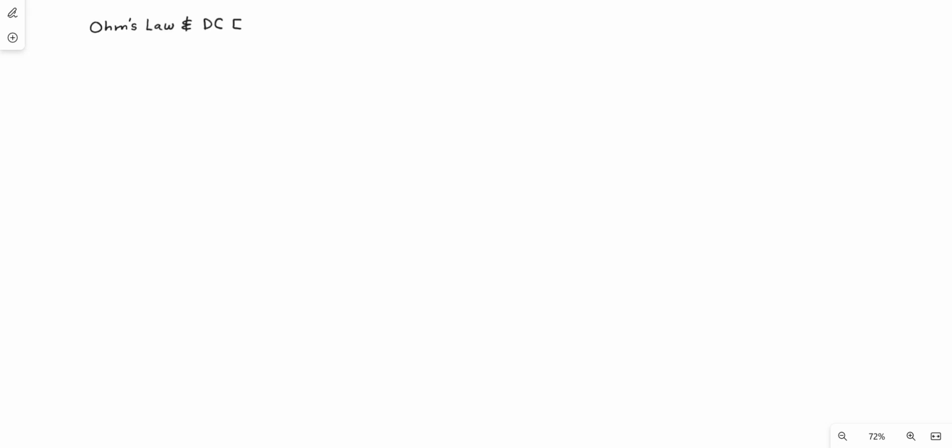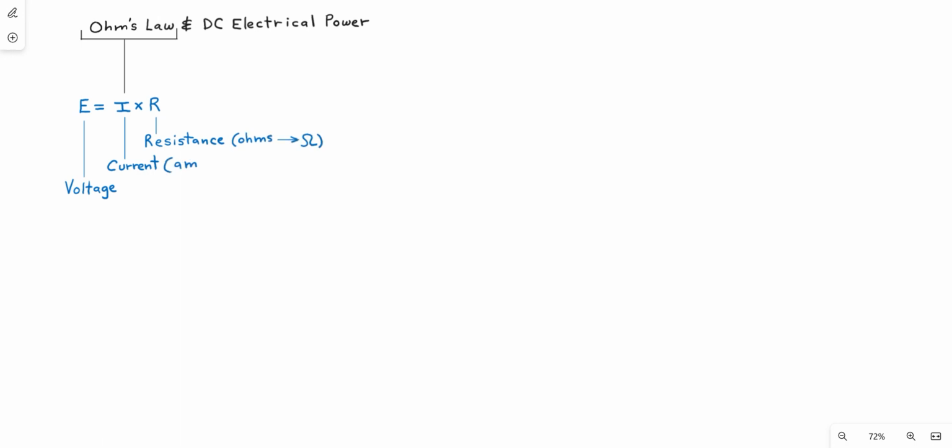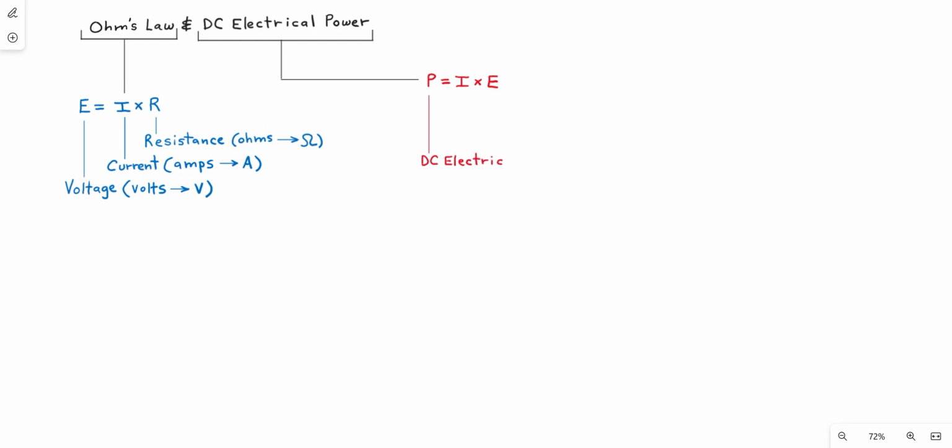So in this video tutorial, we will be covering Ohm's law and DC electrical power. Ohm's law can be expressed as E, voltage, is equal to I, current, times R, resistance, pertinent to DC electrical circuits. Whereas DC electrical power can be expressed as P, DC electrical power in watts, is equal to I, current, times E, voltage.